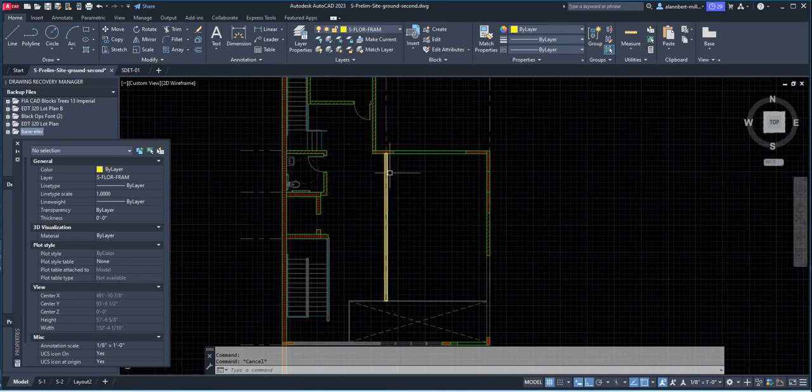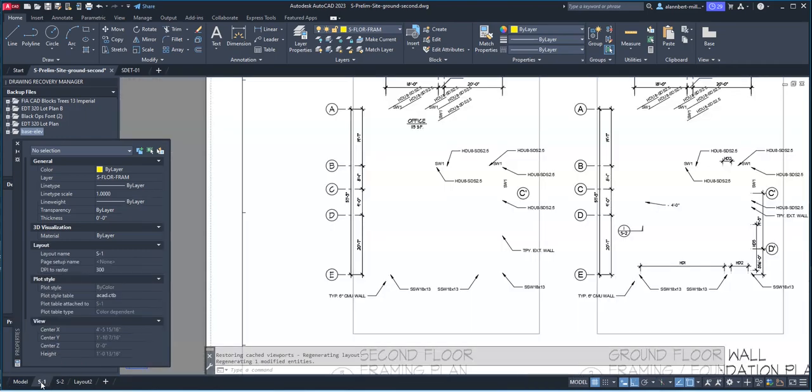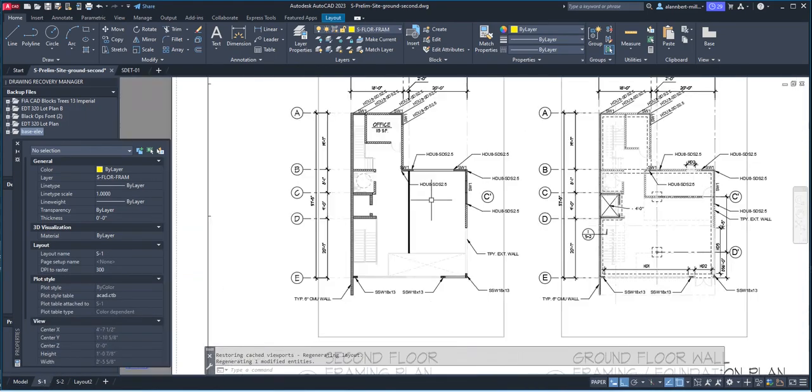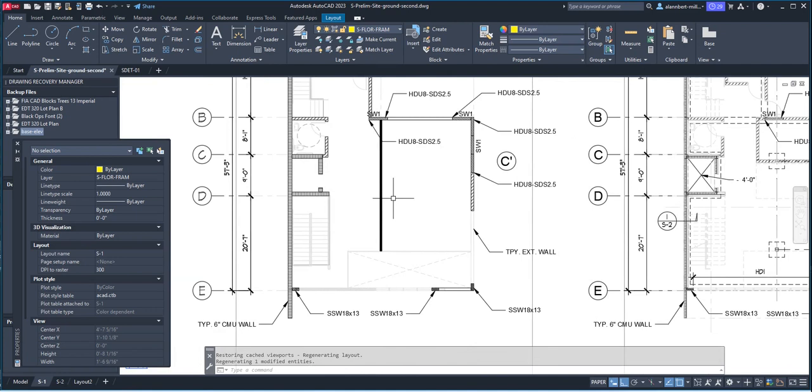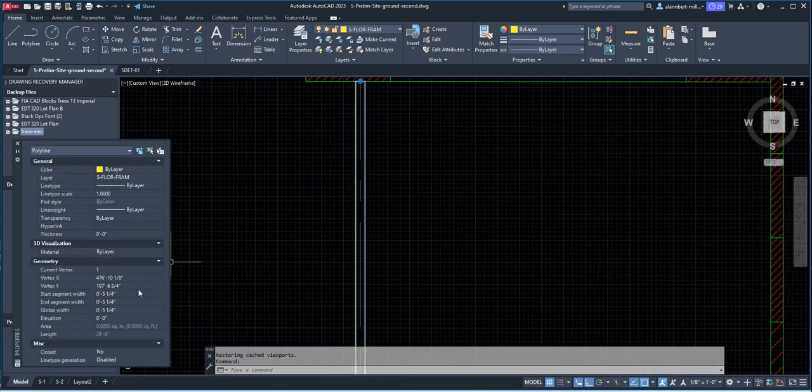Now when you go to this beam, it's supposed to be filled in thick. So if I go to S1, you'll see that it's actually that thick. These P lines do not need to be that thick because it's just a representation on the drawing anyway. So you can make everything standard. And you can change the global width to, let's say, only 2.